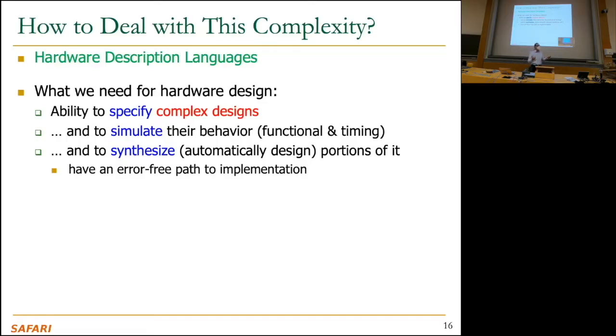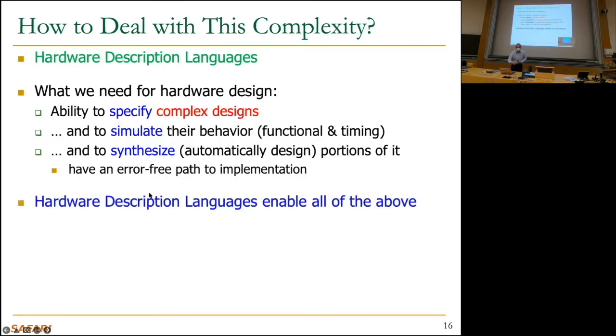Whereas if you actually have a compiler that does that for you, goes from hardware description to logic gates and eventually the hardware, then this could be error-free because you may actually verify the compiler and make sure it works perfectly. You may prove that it's correct, right? That's also another area that's a tough area, but you can gain a lot of confidence in your compiler. Okay, so that's why synthesis is important. So keep in mind that whatever we're going to discuss today can be synthesized automatically into hardware logic gates.